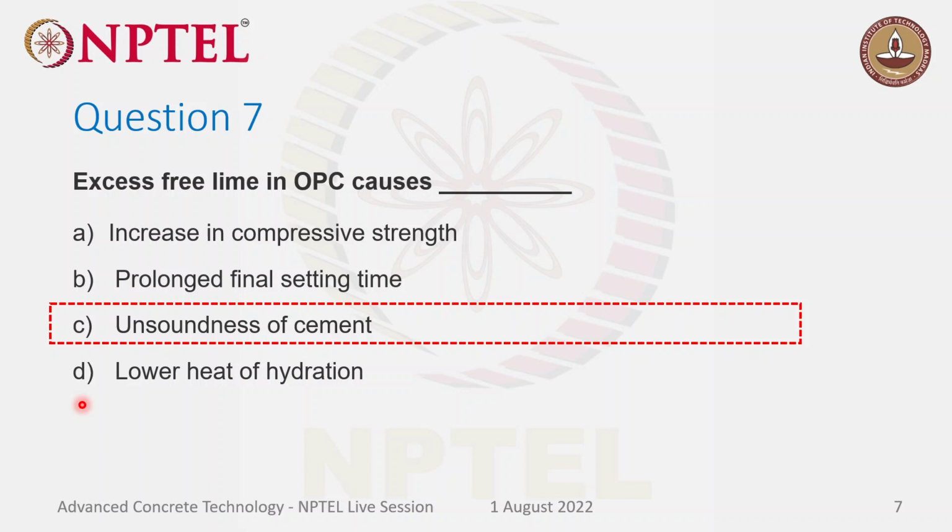Which type of test do you suggest, for water or cubes? You can test the curing water. You're asking the type of test? You can check the chemical content. You can use ICP-OES, inductively coupled plasma optical emission spectroscopy. You can do the chemical analysis of the curing water.